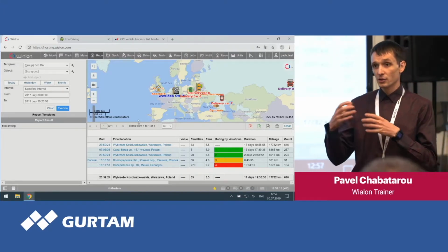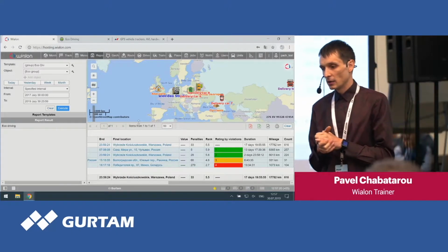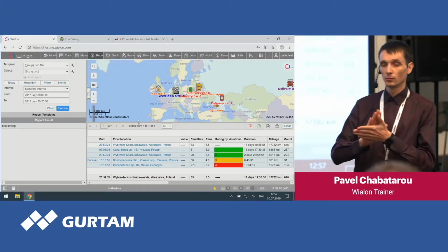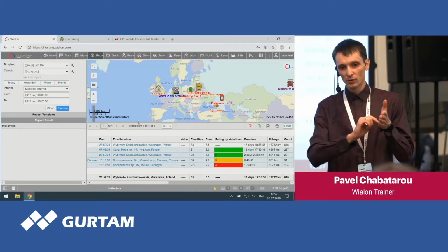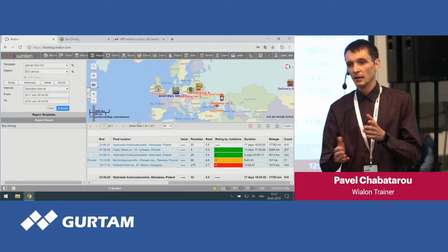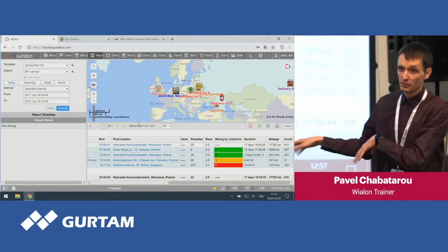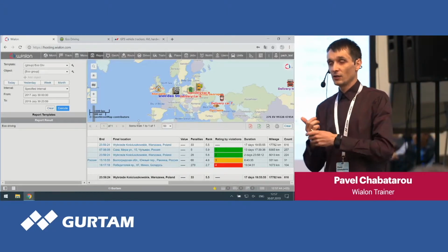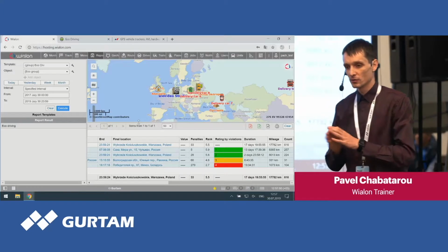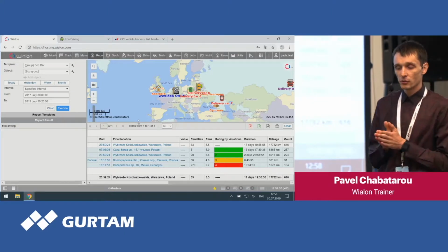And there is some information that is available in open sources. For example, the German Engineering Society has their own webpage where they posted a similar table for trucks. If a truck has a certain weight, then the violation should not be more than 0.24 Gs, for example. If it is carrying a trailer, then the violation should start at 0.14 Gs. This is for an example only. So there is only one suggestion: to make some research.